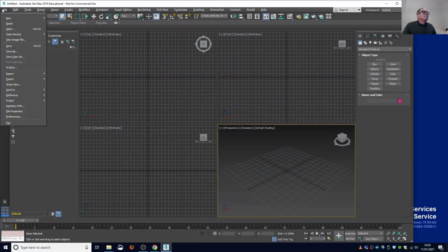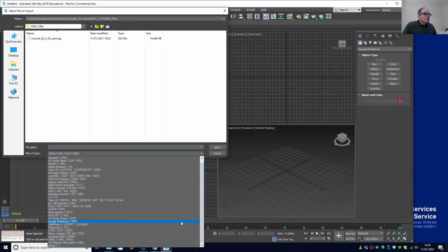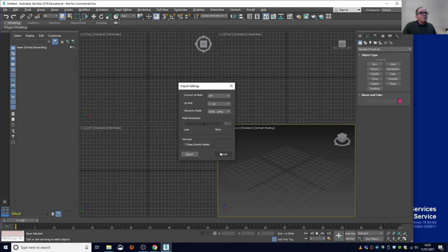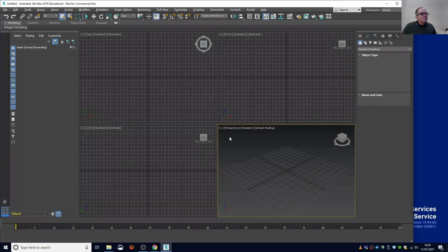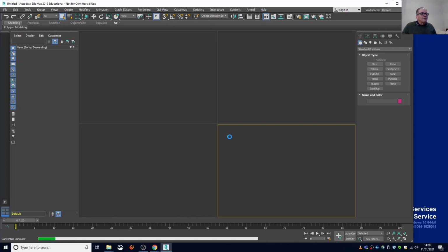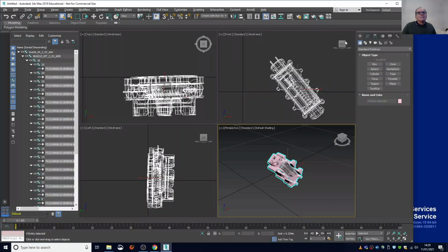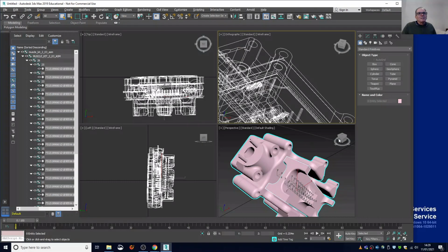And we're going to import an STL file, the STEP (STP) file, sorry, the step file. So step, and here it is, and you open that, and you don't convert again, and you import, and again we're going to have here progress. Here we are, 25. It's going backwards, and you should have, okay. So here we are. Here is our object, and again we have it here as a solid.